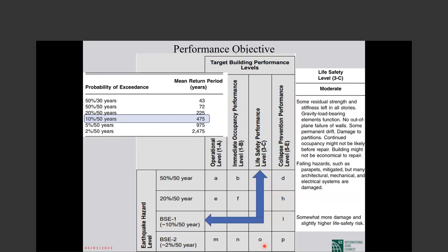Explicitly, you check the level of damage the building will have under that earthquake. So you check, not just increase, for example, the importance factor, increase the base shear, and hope that the behavior of the building, instead of life safety, goes to, for example, immediate occupancy. We hope. We don't check. But here, we check. So there is no need for the importance factor.